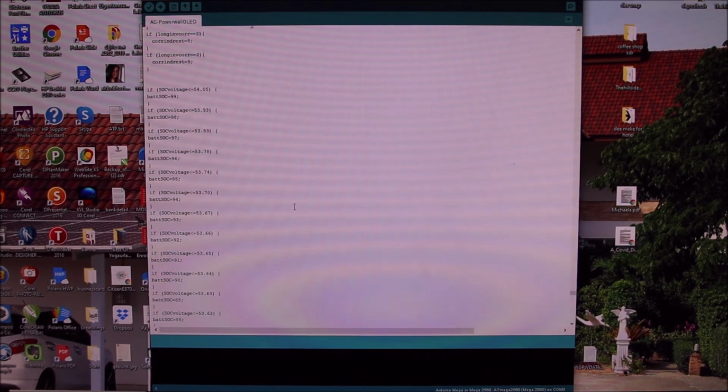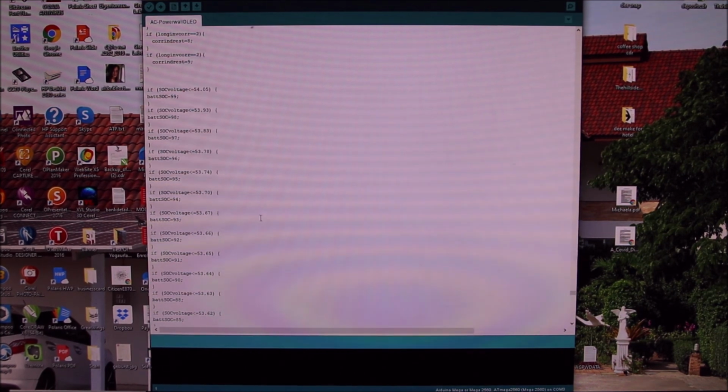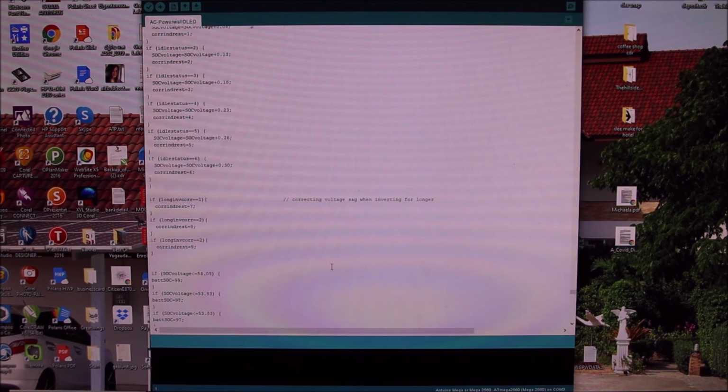There's only one voltage curve per chemistry, which I put in. It is basically an early resting state voltage curve. So after charging, charges off, then 1 minute resting, and then I read the voltage, and the voltage is then translated to a state of charge after all those other corrections are done.